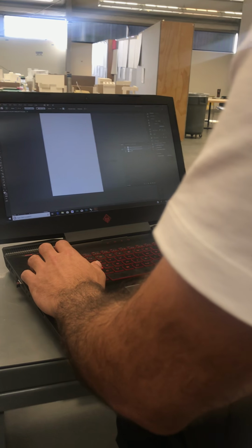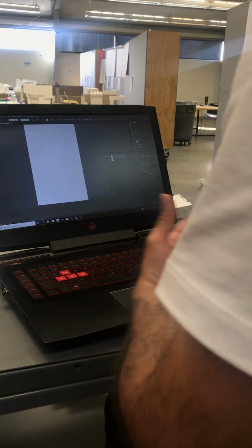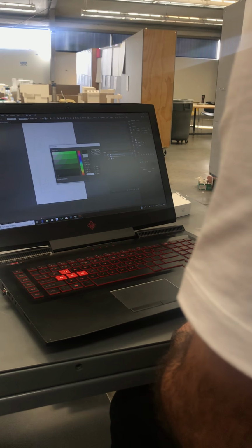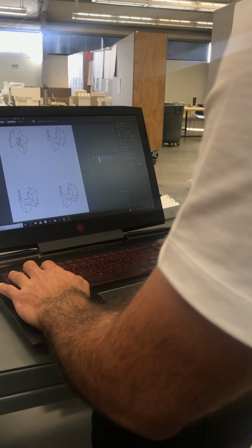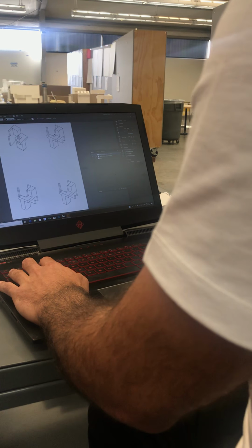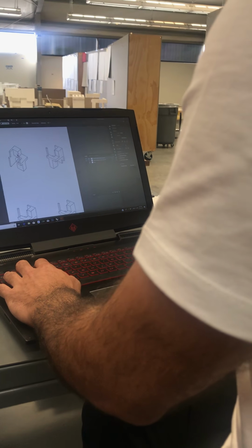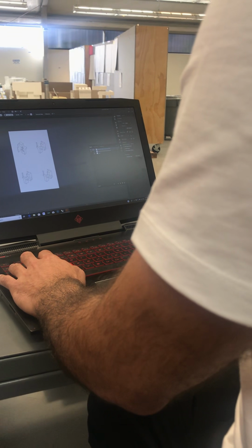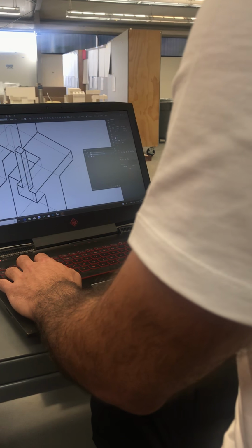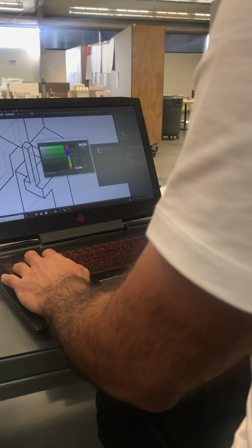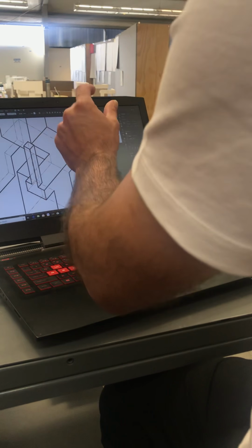So I also want to take that below the visible line, and for now I want to select my visible lines and make them way dark. So I'm going to make the line black, and 1 is probably fine. So here I see my things, and if I hit show hidden line, I can see those in the background. I think the hidden lines are reading a little too light, so I'm going to lock my visible ones and select my hidden ones, and I'm going to make them black as well because the gray just doesn't read too well.